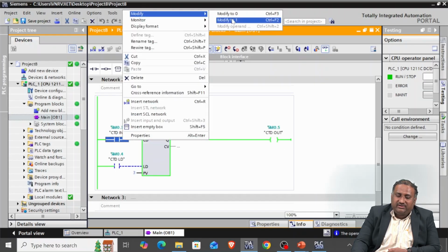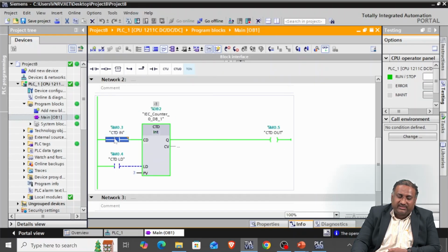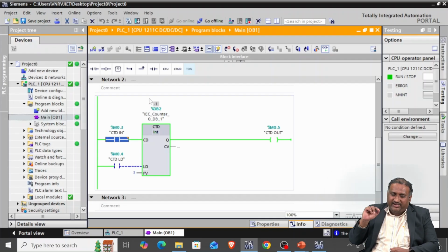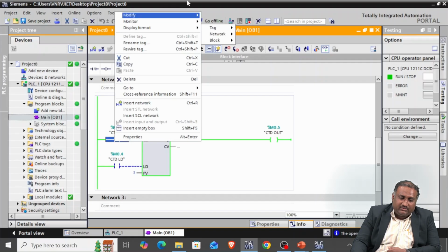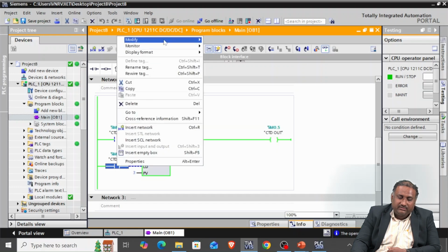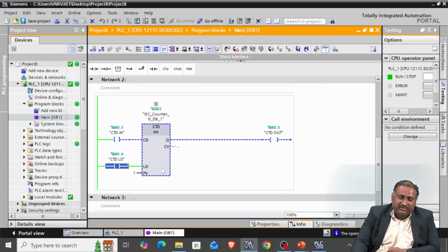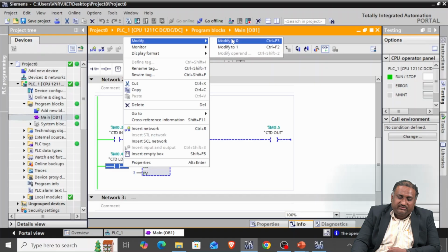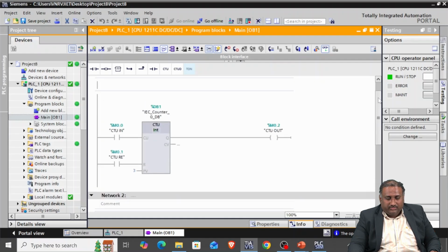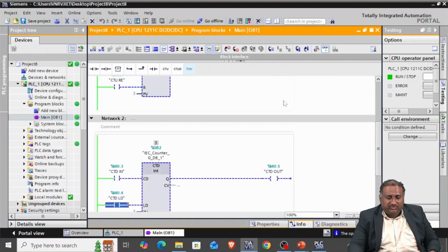And if you give further pulse signals, you can observe that the cumulative value has decreased from 0 to -1. So when you make the load bit high, the system will get reset, and we can use the down counter. So this is about the down counter. So these are the two cases of up counter and down counter.